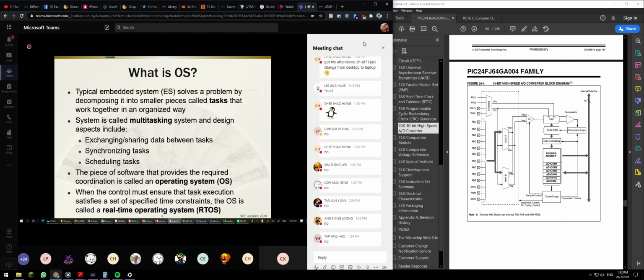What happened to your CPU? Your CPU is also busy. So that's why when an interrupt occurs, it jumps to the interrupt. Things are getting worse if the inside of your while(1) is polling. A lot of things are running, and they keep on running even though you're not doing anything.